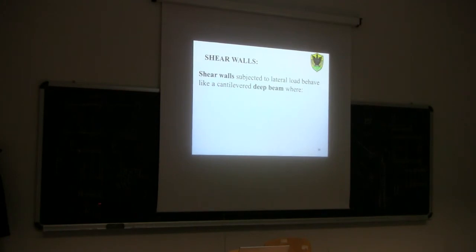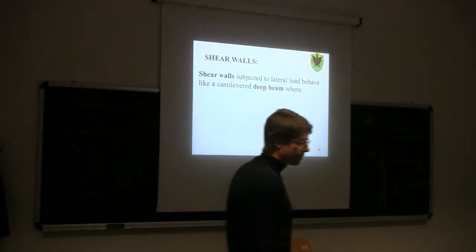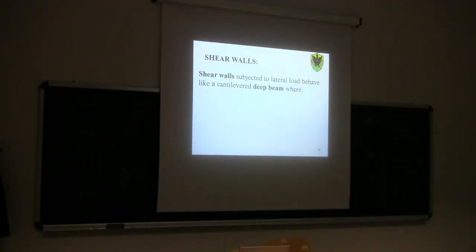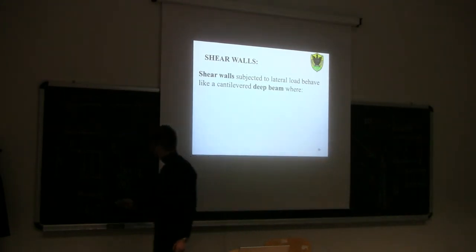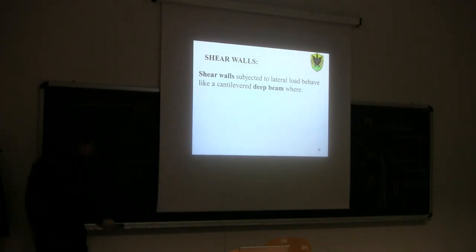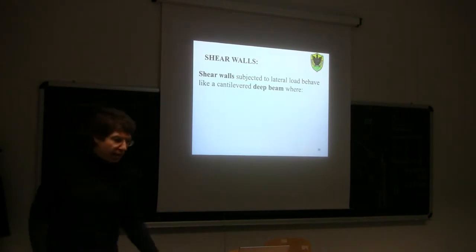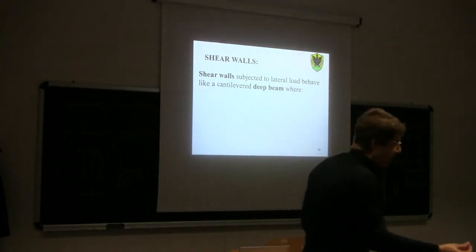So in this case, what would you expect to find as the maximum stresses due to bending moment? So you would say, look, here I have my maximum, what? Here, tension or compression? Compression. Here I would have the maximum tension, and here almost nothing. So I would say, well, this one almost zero. If you wouldn't remember all the formulas, well, probably you remember the Navier formula, they're not so complex.